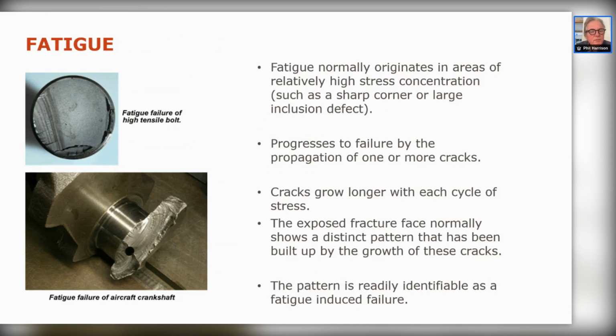What happens with it, the fracture will initiate somehow at a surface. And again, if you have something which will amplify a stress, for example, if it is a thread, a change in section, if you have a change in section which is very, very sharp or very, very rounded, can greatly affect the lifetime of the component. Fatigue life is really, you can have up to 90% of the fatigue life, or 99%, taken up just by initiation and growth of materials.